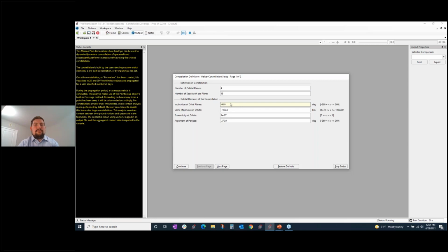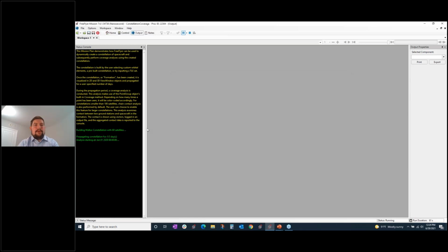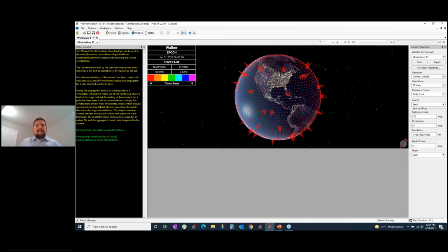My inclination is going to be at, let's do 50 degrees with an SMA of 7,200 kilometers. And we'll leave the rest there. And I'm going to not perform contact analysis. All right. So I'm going to go ahead and build that Walker constellation with 60 satellites.